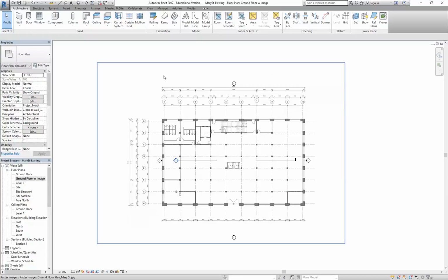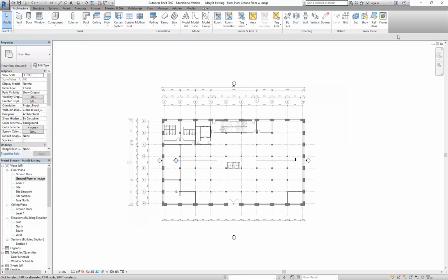You don't go and draw the walls usually, you'll set things out roughly using construction lines. So you should be thinking the same way with Revit, and use reference planes, like construction lines, to set those overall dimensions before you try to draw some walls. So that's what I'm going to do. I'm going to click on the reference plane tool,